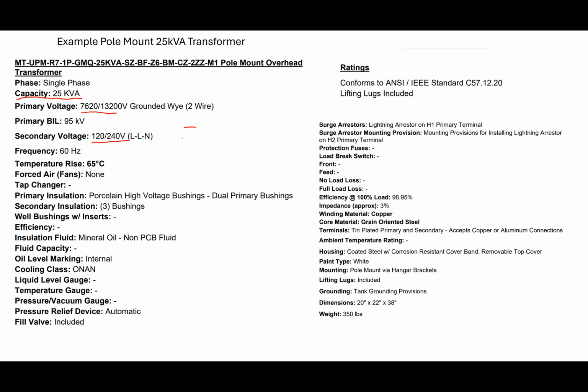Just to be clear, we're not going to deal with this, but if you're interested in it, that secondary side is itself a transformer. What they do is they quote unquote center tap it. So the transformer we'll look at Monday is center tapped, right? So what they typically are doing is they're grounding the middle of the winding.